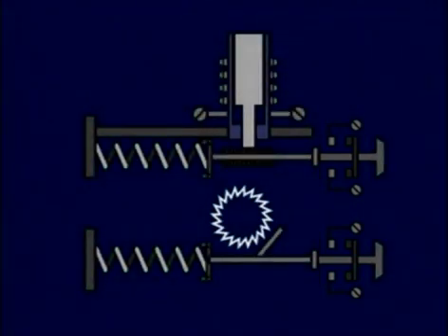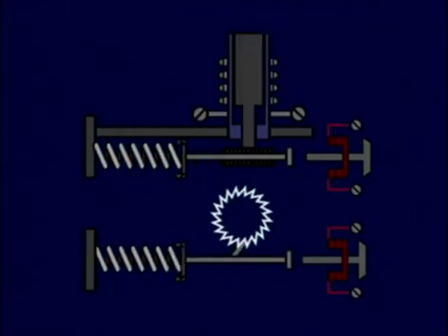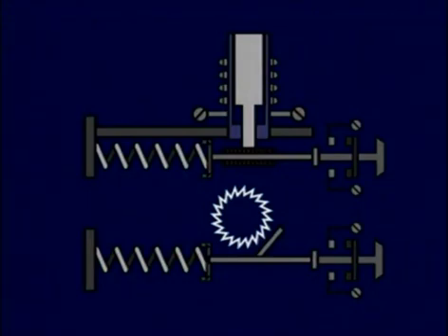When the solder-like melting alloy has cooled down to a solid state, the overload relay contacts can be reset to the normal state. If you try to reset it while the alloy is still liquid, the contacts will open because the ratchet will not be able to hold the pawl mechanism.